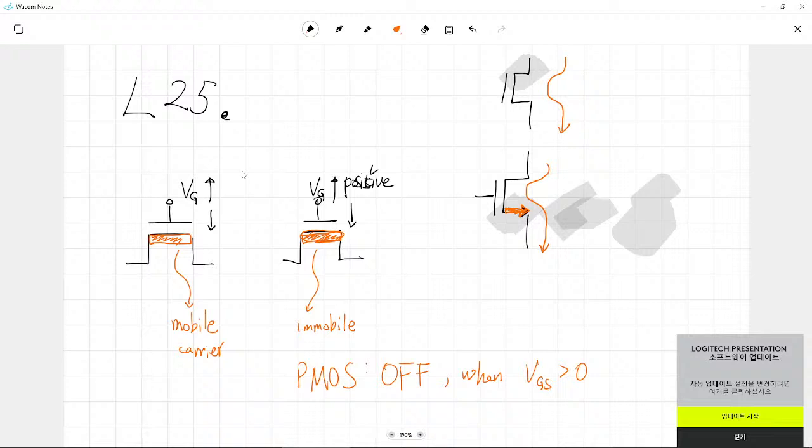So one rule is that we have to attach an arrow here, and if we follow the current direction as the direction of our arrow, then we add our arrow in this way. Simply speaking, when you look at the symbol of a MOSFET, the arrow shows which one is the source, and the direction of the arrow shows whether that is really an NMOSFET or a PMOSFET transistor.